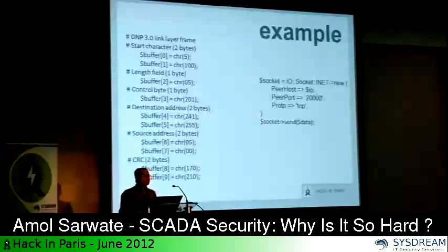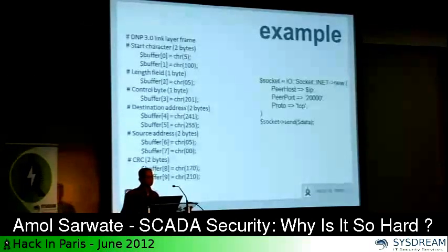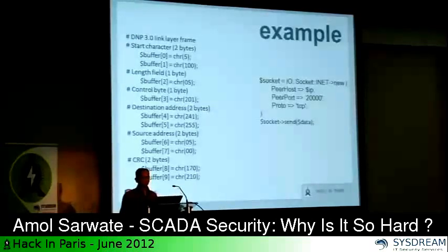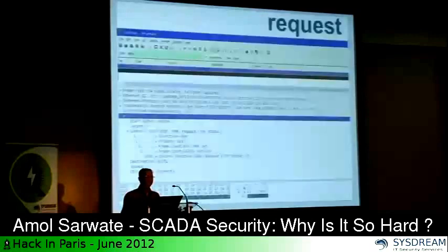So again, a simple Perl example, which creates the packet, fills in your buffer, and this example again is from the SCADA scan tool that I mentioned to you, that you can download at the end. Source address, destination address, CRC. This is for presentation, so I have hard-coded the CRC, but in reality you would calculate it, and you send away your packet on the TCP port.